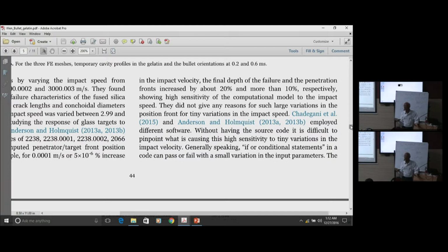So I recently had a student who graduated. He was using damage. I think some of you have been asking me about damage. So he was using Abaqus. He gives me plots. He says damage is 0.59. Of course, the element is not deleted because it has to be 1 for it to fail. I said, come on, this is garbage. I mean, how can we tell anybody this is 0.99999, 5 times 9, and we are not deleting it? And I'm not going to sign on it.